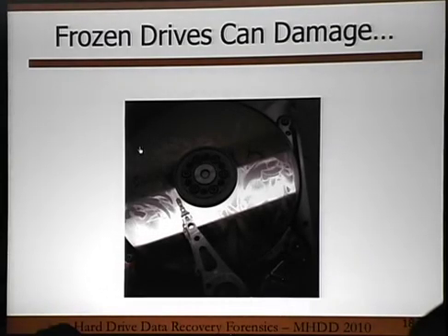Frozen drives. Now, a lot of people go, oh, this is a myth, whatever. It really isn't a myth. It does work. Unfortunately, it's not the best thing to do to a drive. If you freeze a drive, basically the idea is there's something that might, maybe the board or something like that is damaged or the contacts have moved away from each other from heat or something. And when you actually are freezing the drive, it causes everything to contract. And then maybe you actually have a contact or something that will survive for a little while till it warms up again and it dies.